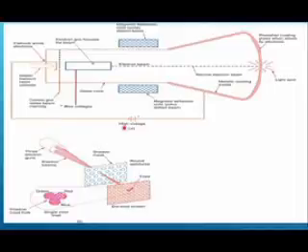A picture tube is a vacuum tube called a cathode ray tube. Monochrome and color picture tubes are available. The CRT used in computer video monitors works like the TV picture tube. The tube is housed in a bell-shaped glass enclosure. A filament heats a cathode that emits electrons, which are attracted and accelerated by positive bias voltages on the elements in the electron gun assembly. The electron gun focuses the electrons into a very narrow beam.